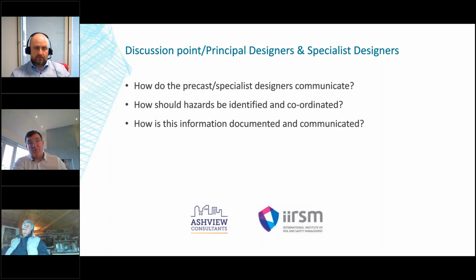And so that feeds into the golden thread of information, which we're all very familiar with, of how the end user, the duty holder of the building, can maintain the building safely as well. So we can all talk about how it can be designed and constructed, but how the building can be maintained safely is a vital part of this as well. And I'm sure we can all agree that sometimes when the value engineering exercise starts to take place in the project, the future maintenance aspect of the building starts to get the proverbial axe. And you as a design risk management strategist, or pre-construction or CDM, have got to dig your heels in as to how that future maintenance will take place and what information will be in the safety file and O&M. So the drawings, workshops, DRAs, and the actual information at the end for the duty holders of the building.